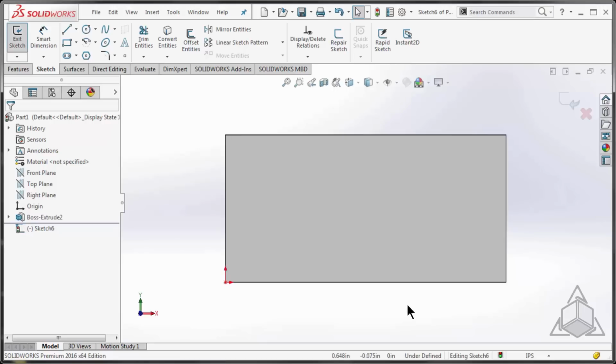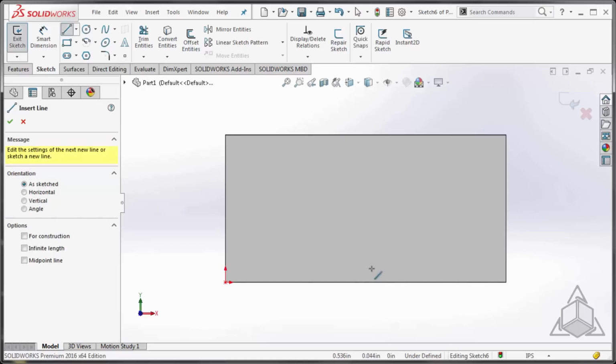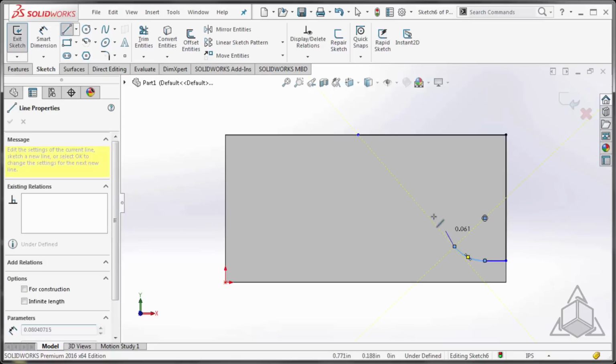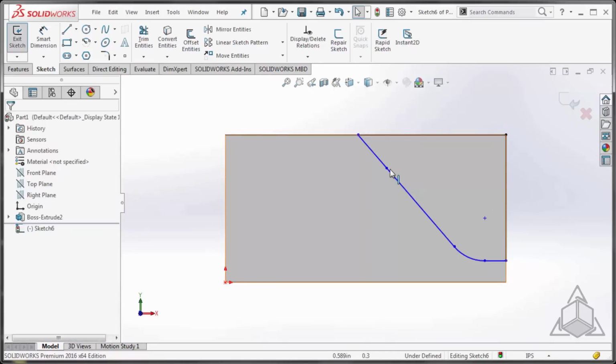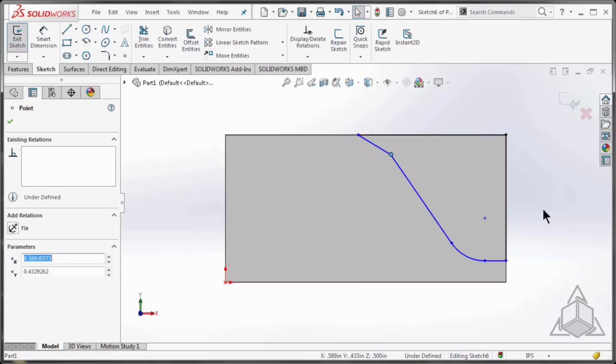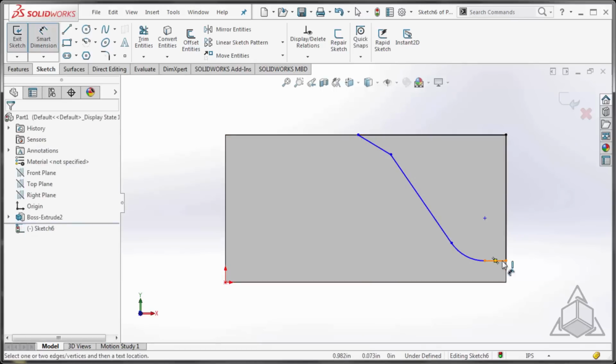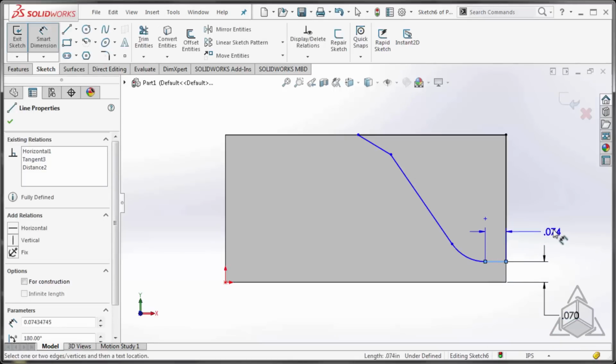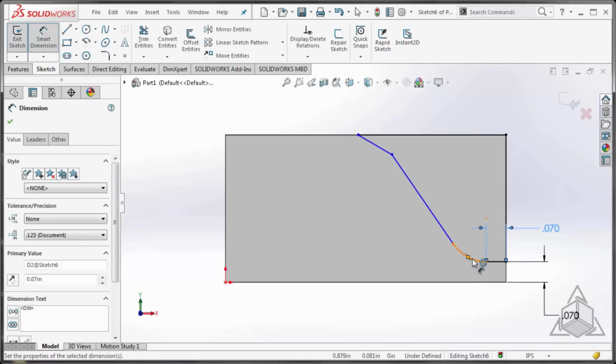Now that I'm in a sketch, I'm going to create a simple closed profile and add smart dimensions to create a weld prep. Make the land and the radius, keep a tangent line up, and I'll just modify this just a little bit. Great. Let's go ahead and make that thickness here. Add the length. And now here to finish up these last angles,